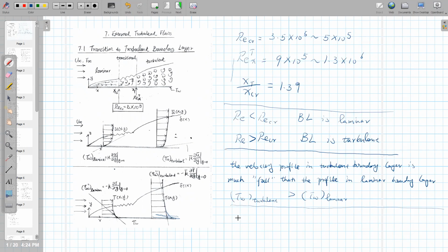the turbulence, similarly, will also make the q_wall for the turbulent case larger than the q_wall of the laminar case if T_w is constant. For the constant wall temperature case, the existence of turbulence will also try to bring more heat from the wall to the flow. So generally speaking, this is the effect of turbulence for this problem.